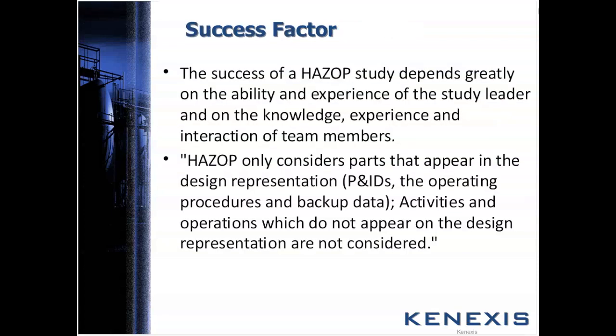So, real bottom line, the success of a HAZOP depends on the building experience of the study leader and the team, and it depends on the process safety information and the materials that you have to analyze. They need to be accurate.